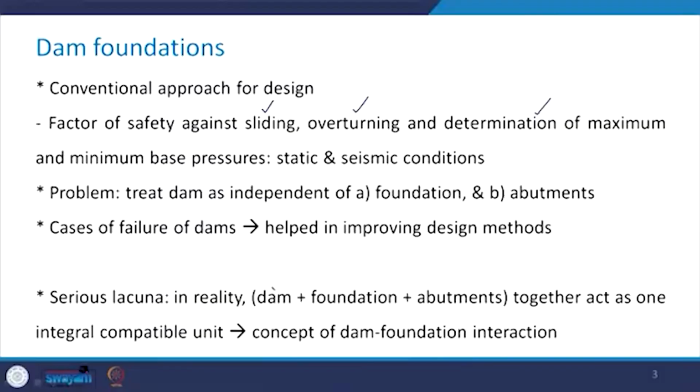In reality, what happens is that the dam, foundation, and abutments, all three components, act together as one integral compatible unit. And you cannot analyze only the dam body separately without considering the effect of foundation and abutments.